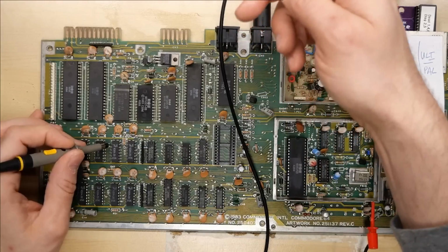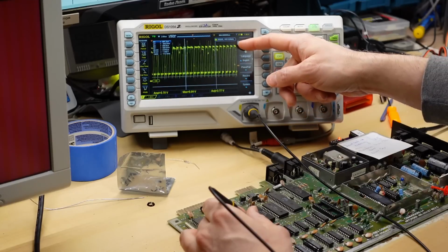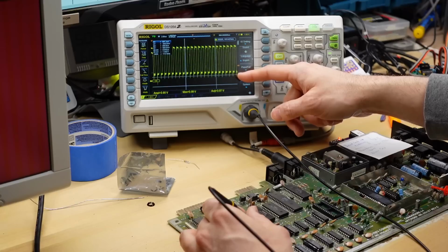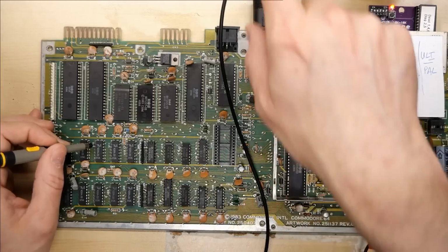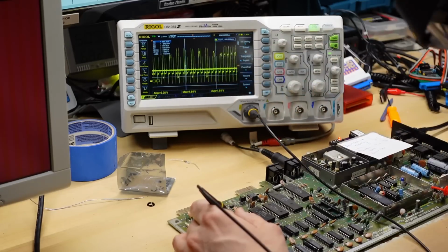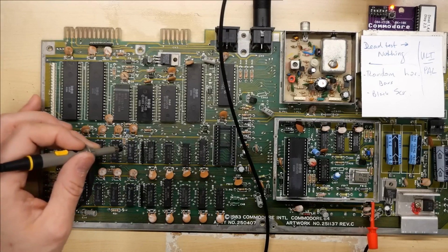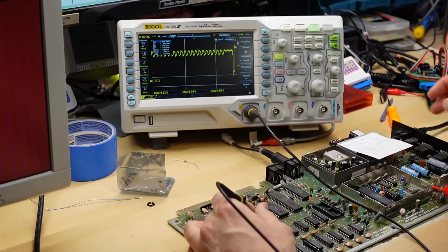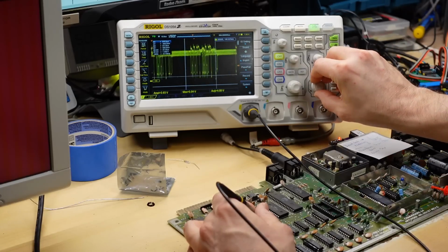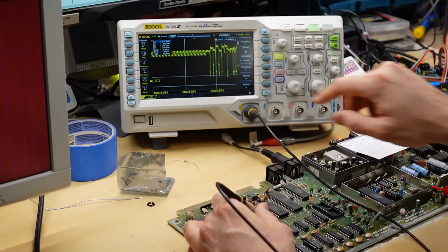Okay, so this one actually looks pretty normal. It's going from 5 volts all the way down to close to 0 volts. This one, you notice it's got this line here in the middle. It looks very abnormal. Okay, this one here, it's just sort of stuck. Let's shrink this down a little bit. No, okay, there's activity. So I'd say that's not too bad.